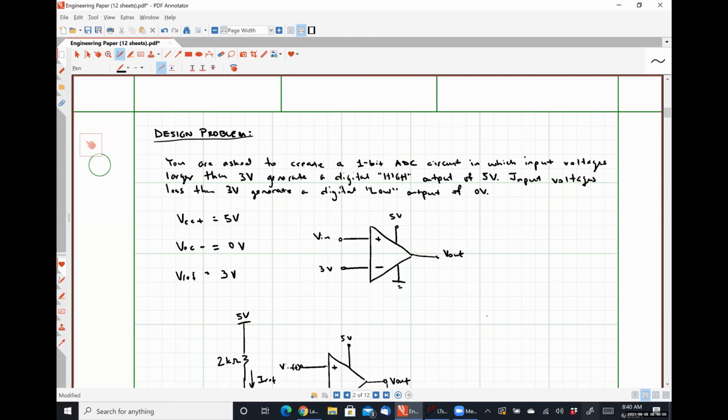Internal to the multimeter, there is typically a very, very large resistance on the order of tens of mega ohms. So if you were trying to measure the voltage drop, the reason it uses that very large resistance is because it's placing that large resistance in parallel with whatever you're measuring and then measuring the voltage.